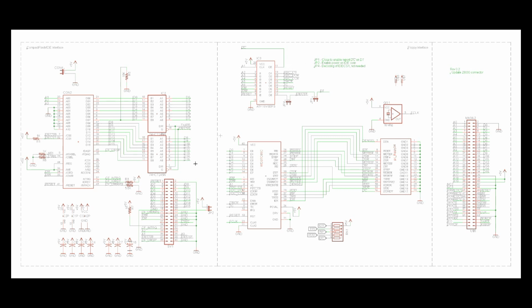Over here is the floppy controller. Now I think this is a design I borrowed a few times from Sergey's Zeta 2 computer. So it's got a WD37C65 hooked up to a 34 pin PC floppy connector. It needs its own crystal, its own 16 megahertz. It needs a few pull-ups over here. And then we need to do some I/O address decoding for it.